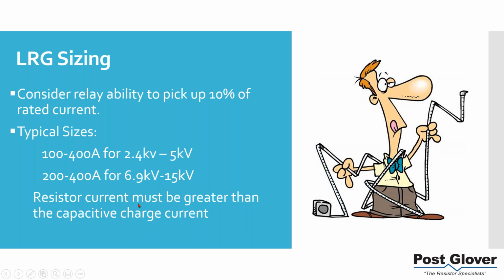I would say if you have a lot of snubbers, or a lot of things that actually contribute capacitance, and if you think you have a high level of capacitance, you may want to worry about it. At high resistance ground, you almost always want to worry about it, but at low resistance ground, it's very rare.